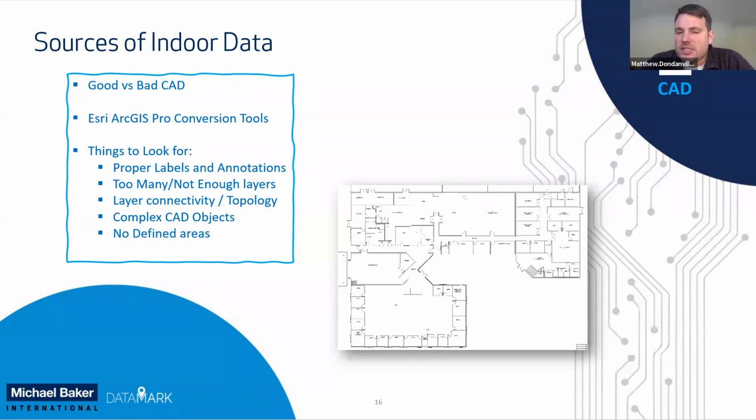So good versus bad CAD data, it's definitely not all equal, and it's a big consideration. But if the organization is living by some standards that can be deciphered, it can be as easy as doing some basic mapping of CAD layers to the indoors data model on a single level of a building, and then extrapolating that and automatically importing hundreds of buildings. So the key, and one of the takeaways that you will come away with from this whole presentation, is the importance of these standards to make indoor mapping really attainable on a large scale.